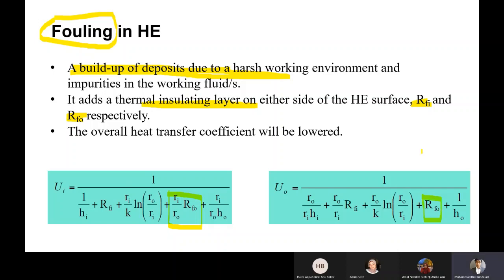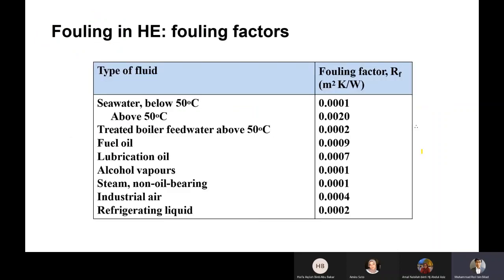That's the thing. This gives a theory why, for example, a chemical plant needs an overhaul every year. They stop it for a few weeks and do all of the cleaning, restore the performance, clean the heat exchanger, and wash out the foulants that stick on the surface of the heat exchanger. So what are those values?